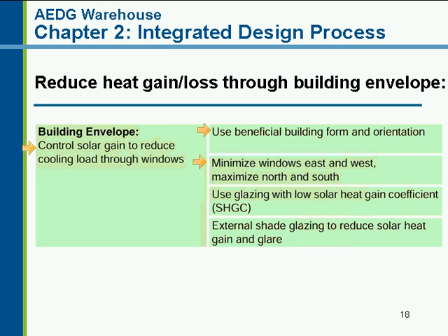You know, if you've ever been in, for example, a passive solar greenhouse or a sun space on the south side of the building, and people say, oh, this works so great during the winter time, and yet in the spring and fall, it's hot here all the time. That's the exact example of something that is not well designed. It means it's got too much solar gain. It doesn't have storage to moderate the effect. And so too many windows can cause problems, can cause discomfort, and that'll mean callbacks for you if you're the contractor or designer on this.